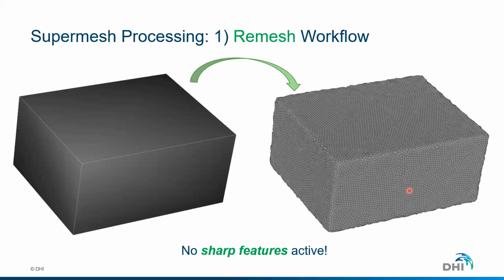There are also new concepts in this framework. There is the possibility to maintain or preserve what we call sharp features. To explain this in simple words, you see this cube. If I do not preserve the sharp features, FEFLOW GeoD could basically round the geometry, because there is no direct information to tell the algorithm whether the surface will be preserved or not.